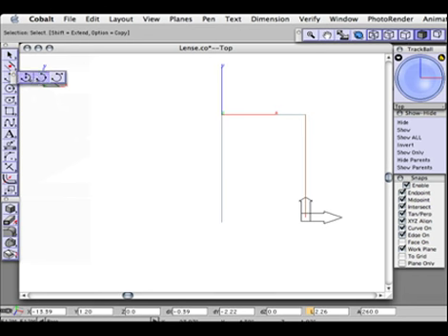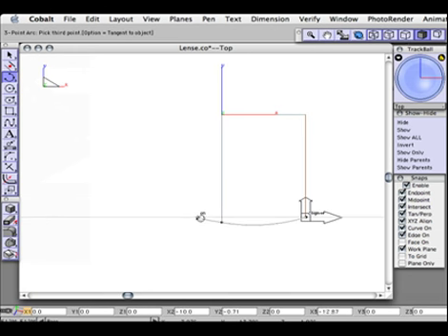We use the 3-point arc tool, and we're going to also turn on the work plane. So we're going to click our first point at the work plane, second point at the endpoint of the line, and then using the drafting assistant, we're just going to snap to a point that's based off of the first point we clicked. In the message line, I'm simply going to change the X3 value, which is the third point we clicked, to -20, and this will make our arc uniform on both sides.